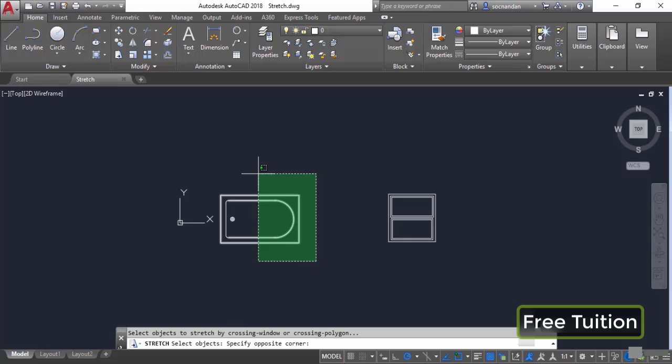Now all the objects which are completely inside this crossing window will remain unaffected, and all the objects which are completely outside this stretch window will also remain unaffected. So in this case, this line segment, this complete arc, and this line segment, this part of geometry will remain completely unaffected, but the length of these 4 lines will change, because in this case only these 4 lines are partially inside and partially outside.